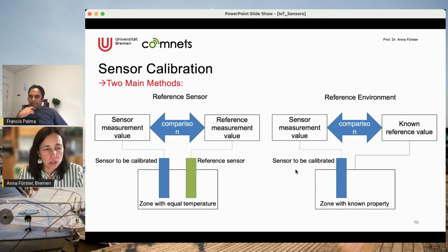It is only about how to interpret the values coming out of the sensor, because the raw values from the sensor are actually an electric signal, either voltage or resistance and things like that. Those have to be interpreted. The calibration is for reinterpretation, not for changing the input voltage. So basically it's the output that you're talking about, not the input voltage. Yeah.